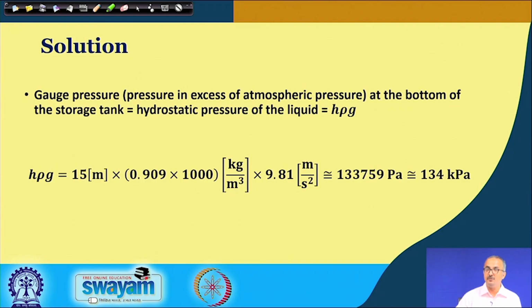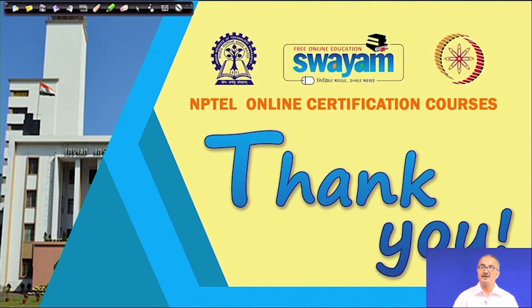So, be careful whenever you are reading a pressure: check whether the pressure has been given as absolute pressure or gauge pressure. Many times we make mistakes by not converting the gauge pressure into the absolute pressure. Okay? Thank you.